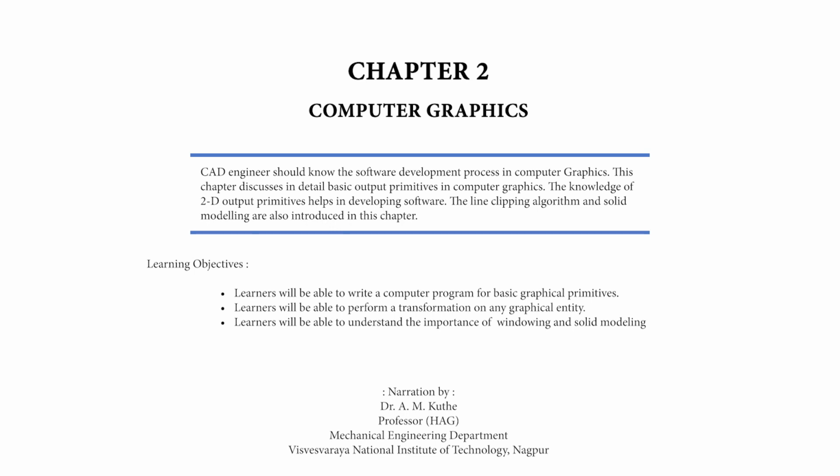The final transformed image of the point (x, y), that is x3', y3', can be obtained for any number of transformations and types of equation. The process of finding the transformed image of the point by multiplying the matrices in order is called concatenation. Para 2.8.5, application of concatenation. Using the concatenation process, it is possible to prove the relation for scaling with respect to a fixed point (xf, yf) and rotation about any point (xr, yr). Similarly, the concatenation process is used for studying the reflection transformation.